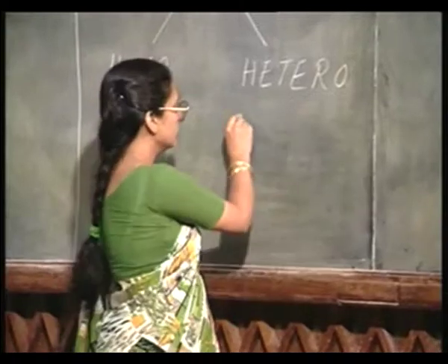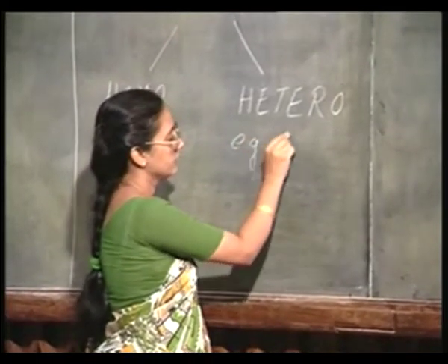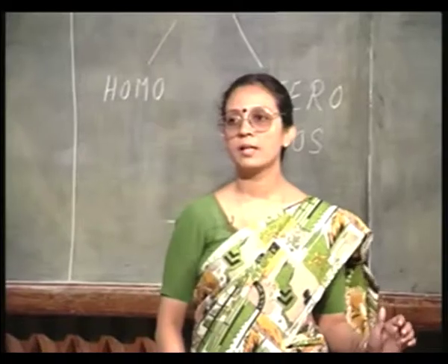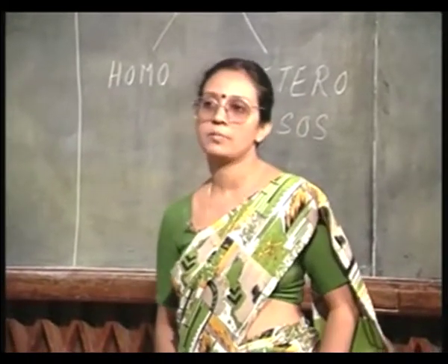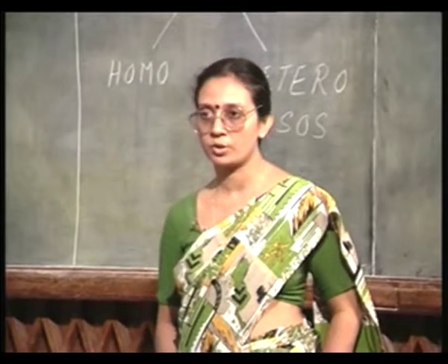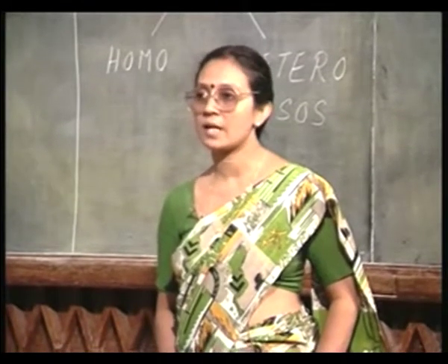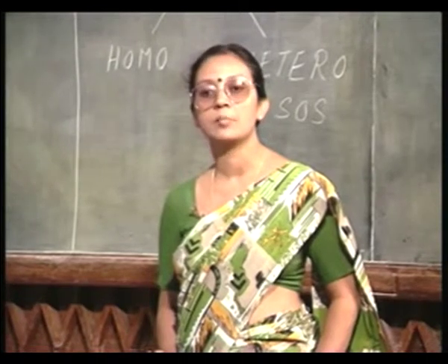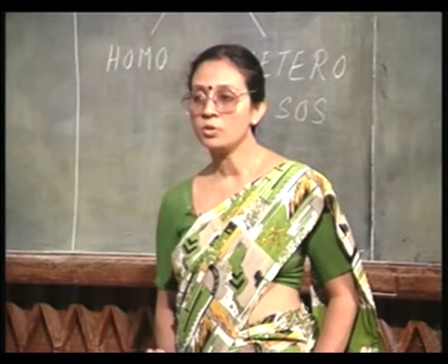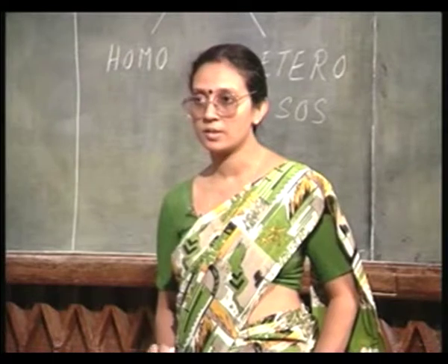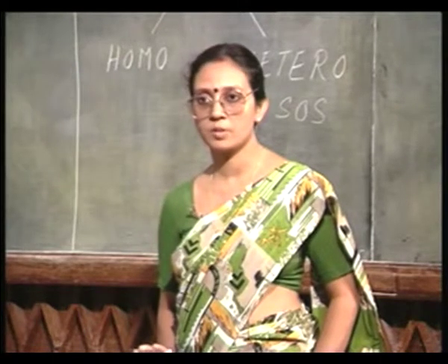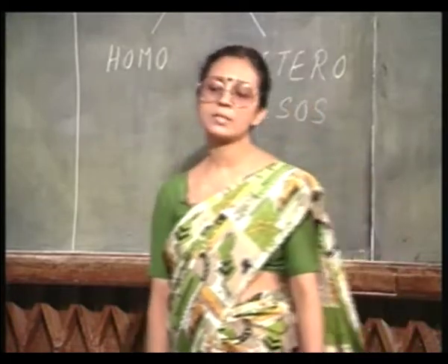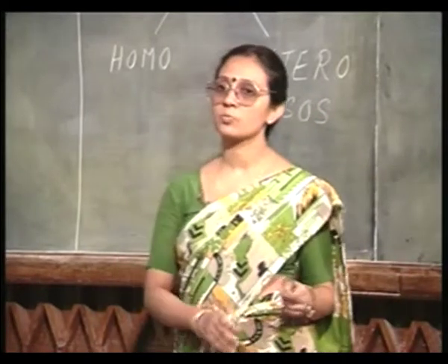For example, silicon on sapphire. Sapphire is actually nothing but aluminum oxide, Al2O3. It has a hexagonal lattice pattern, and silicon, as you know, has a diamond lattice structure. So, two dissimilar materials, silicon and sapphire, we want to grow one on top of the other. So, heteroepitaxy is much more complicated.